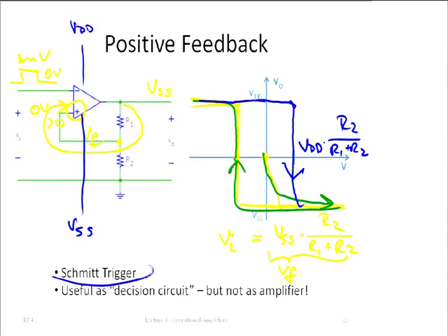Imagine that, for example, you want to build a thermostat. You want to set the temperature in your room exactly to 20 degrees Celsius. The way the thermostat works is that if the temperature is below 20 Celsius, the heater turns on. If the temperature is above 20 degrees, the heater turns off. Most thermostats actually work like this. They simply turn the heater on and off.